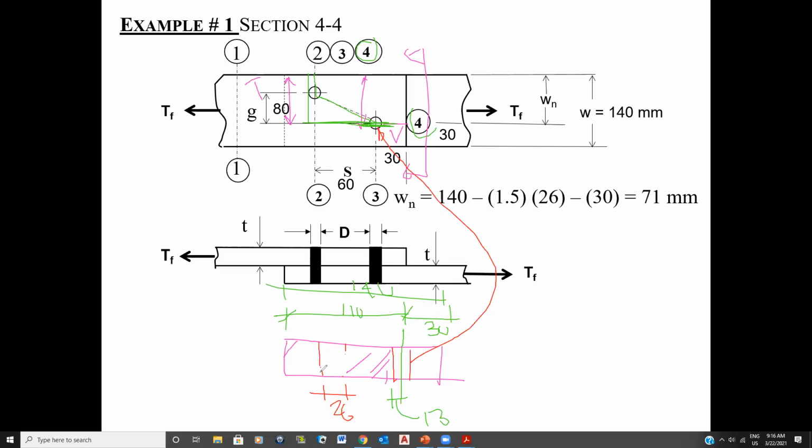So I have the steel minus the first diameter of the bolt. Of course, you want to calculate the area that's here. This part, you understand? You want to be able to calculate the amount of area you have in this failure plane right here.